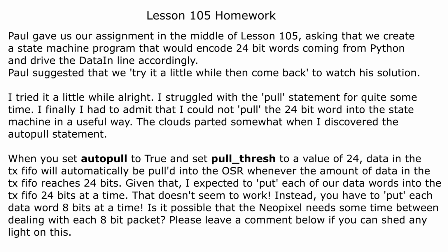Given that, I expected to put each of our data words into the TX FIFO 24 bits at a time, but that doesn't seem to work. Instead, you have to put each data word 8 bits at a time. Is it possible that the NeoPixel needs some time between dealing with each 8-bit packet? I don't know. Please leave a comment below if you can shed any light on this. Let's have a look at the code.